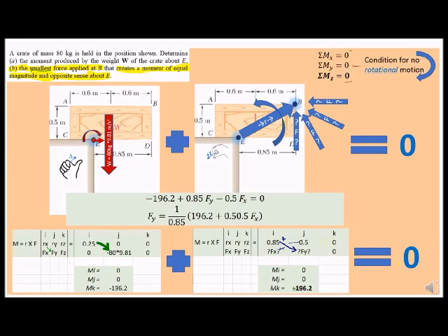So we need to get that 196.2 no matter what we do. Writing out the equation for this cross product, so we have everything going on the red side to create that clockwise rotation. And we also have everything going on for the blue side, and this we're going to just keep in terms of X and Y instead of plugging numbers in. And remember, the point of this is to create an XY combination that produces the smallest force on B. We want to make life easy on ourselves.